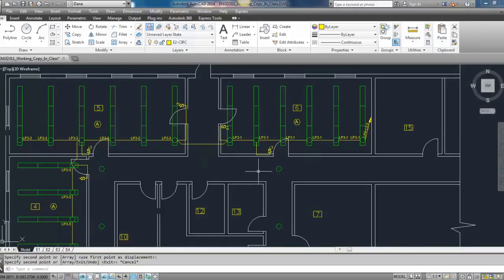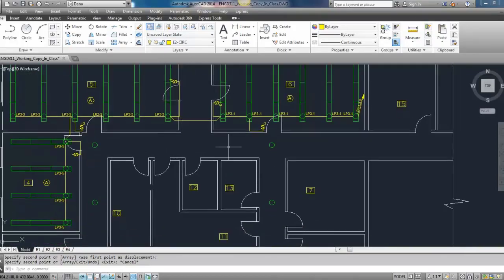hallways, it would make sense from this point of view, but it would be a little too far away for this one here. I think that there's going to be not enough light. We'll have a little dark spot sort of right about here if we were to place a light here. And we really don't want to place another light here because that kind of creates an unsymmetrical layout for the hallway. So I think what I'm going to do is I'm actually going to divide this space up into 3.